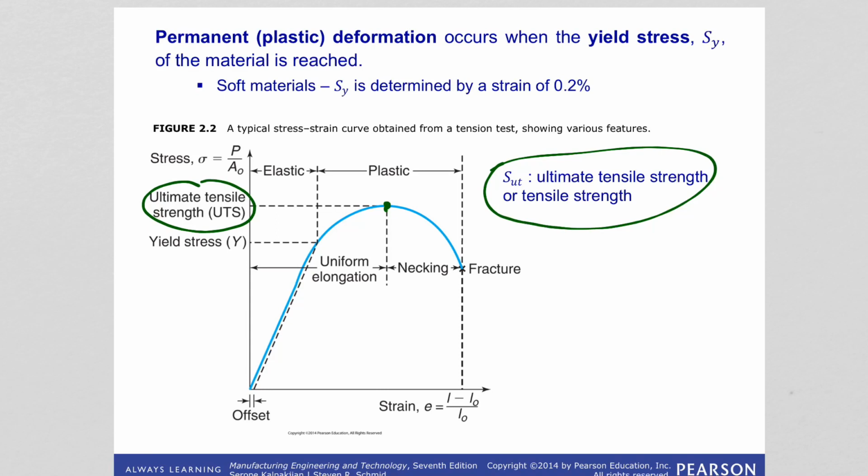Because you know the device only records the force that needs to be applied to keep the deformation rate constant, and then measures the deformation. That's it. So it needs to convert this force to the stress. So how does it do it?